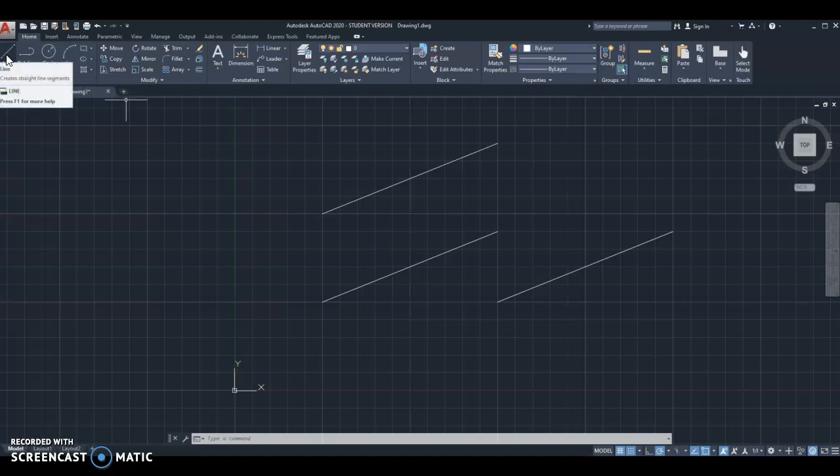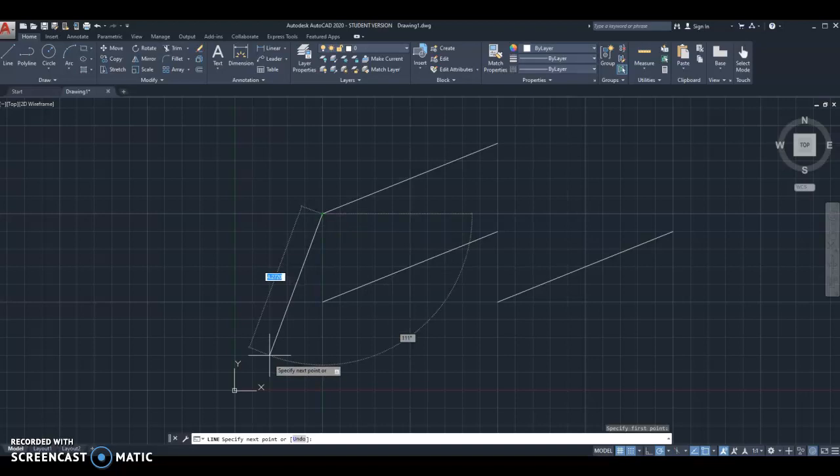So if I wanted to start a line here, and then I wanted the next point to be the coordinate down here of, let's say, 1 inch over and 1 inch up, the absolute coordinate 1, 1, I would have to hit the Shift 3 button, like a number sign or hashtag, and then put in something like 1, 1.